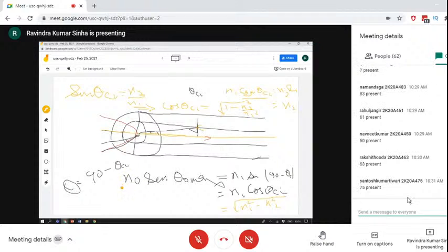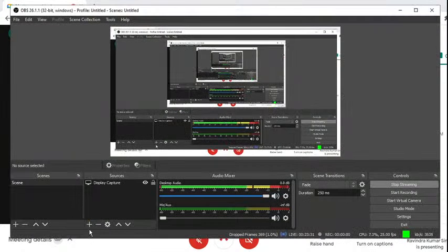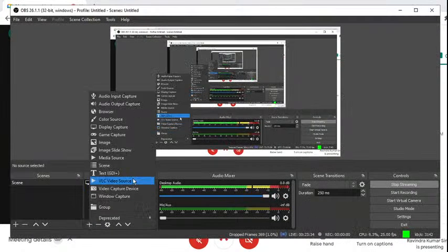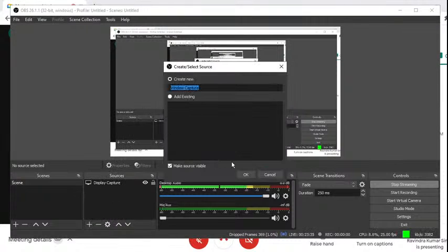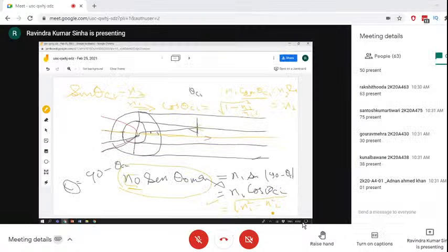Now this is equal to the numerical aperture of the fiber. That is mathematically. Again, N0 is air. If it is water, like if we keep it in the water, then the numerical aperture will be the square root of N1 square minus N2 square divided by N0. If N0 is water, you can write N water. So numerical aperture will be this. It will be rather reduced.